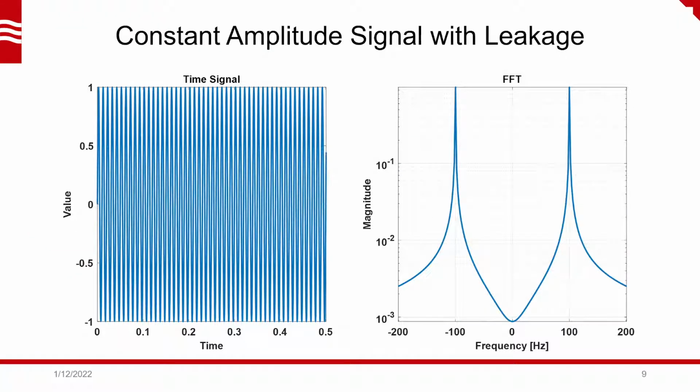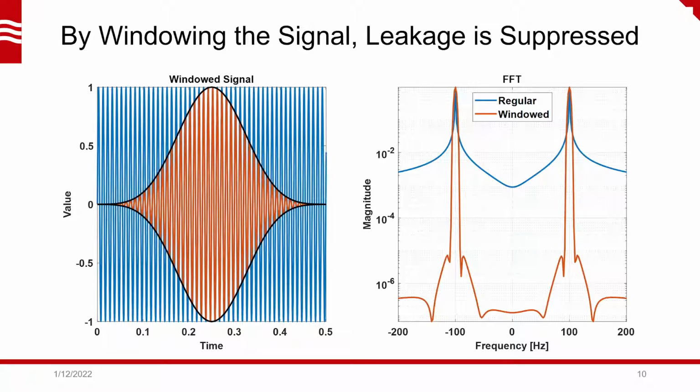So what can we do to mitigate the effect of this missing negative frequency bin leakage? Say we start with the same stationary noise-free but not periodic signal from before, where the exact imaginary complement has all that negative frequency leakage. The thought I had was, if we apply a windowing function to the signal, we can suppress the leakage in the frequency domain. The windowed signal is shown in orange, and the windowing function is in black, where here I used a 4-term Blackman-Harris window.